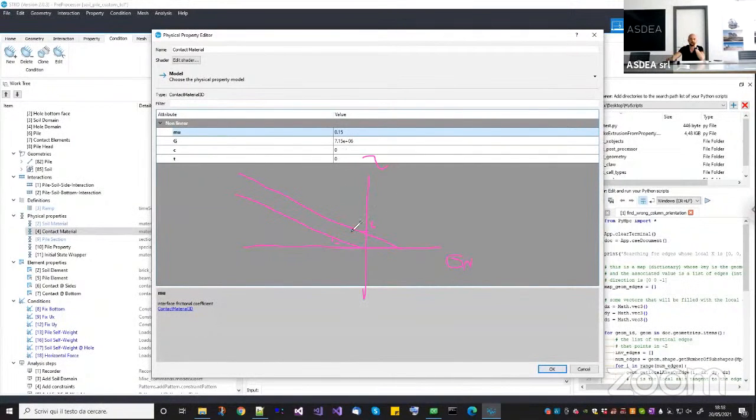And then you have T, which is a tension cutoff. For example, if using this cohesion, the tensile strength coming from the cohesion and the slope of this line is too large for you, you can put a value that can be something like this, okay? So you can put a tension cutoff. So this one will not be considered, okay? But as I said, I'm going to just represent hard contact, so no cohesive zone in between. So this one will be my yield domain.